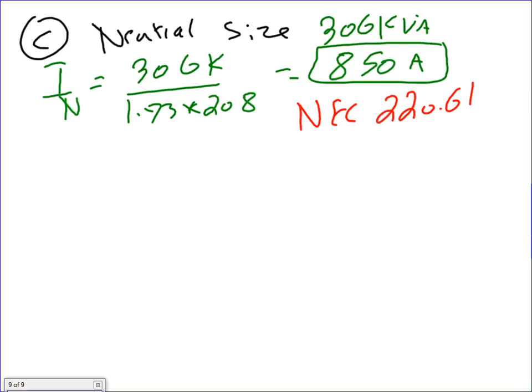It will tell you that you can derate a portion of unbalanced load in excess of 200, especially 220.61(B)(2). If you guys go read that one, it tells you if your neutral is higher than 200, cut anything higher than 200 by 70%. That applies for everybody.